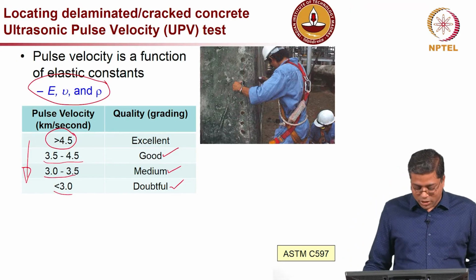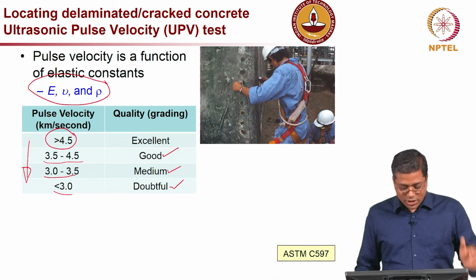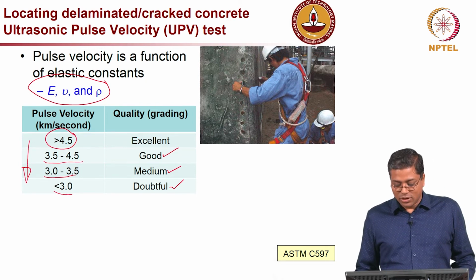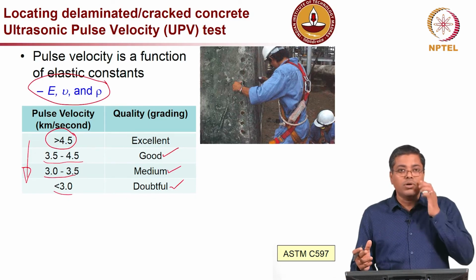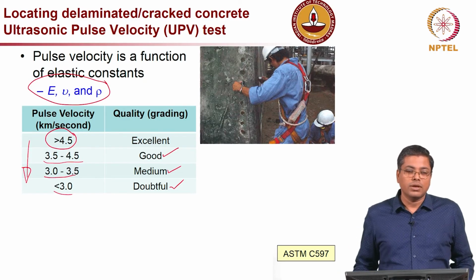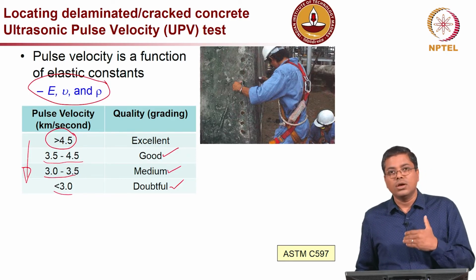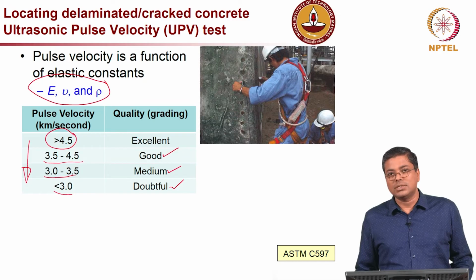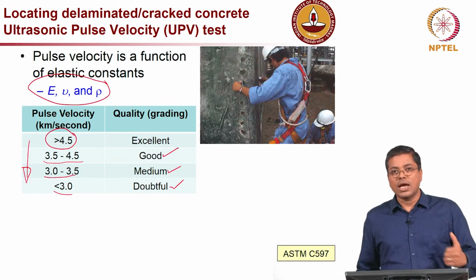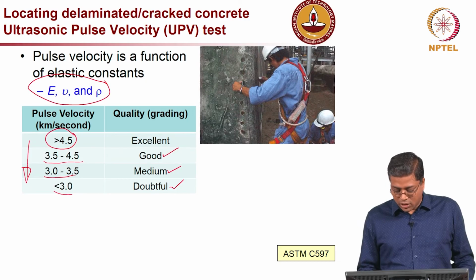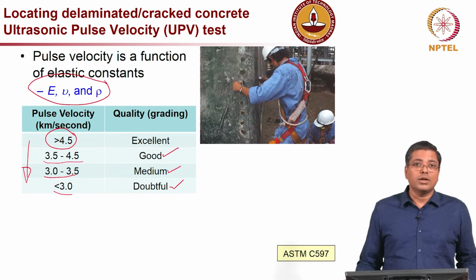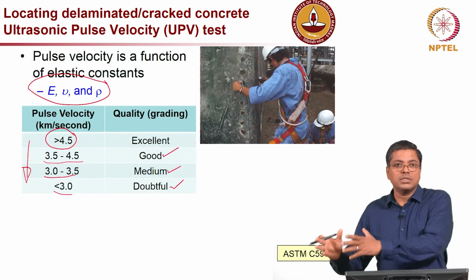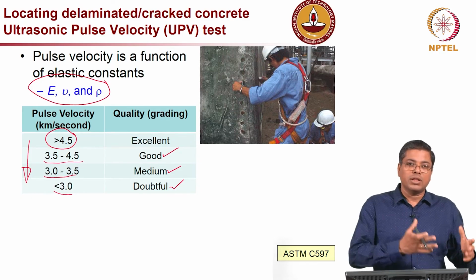So depending on the quality of construction and the inspection which was carried out, the quality control, all these you have to think about. If you are talking about elements which are very large, this is very useful information to give you and also to sensitize people at site. This should be told to the people who are actually doing the work, so that they know that if there is some problem, if there is honeycomb, then they will be questioned later.